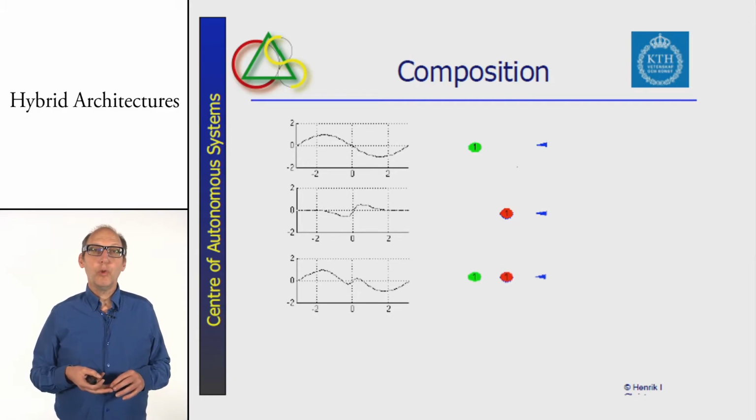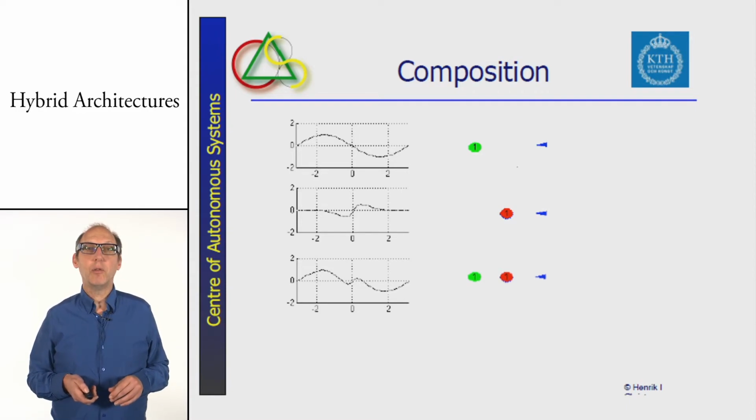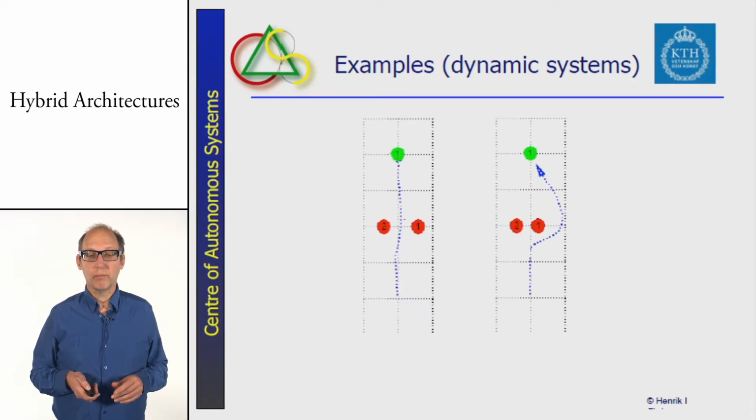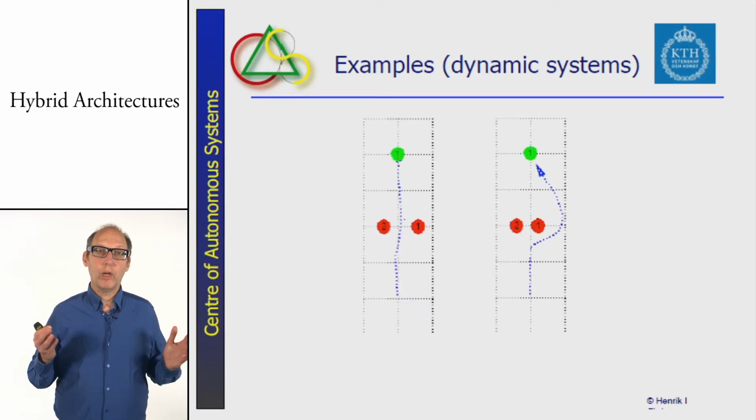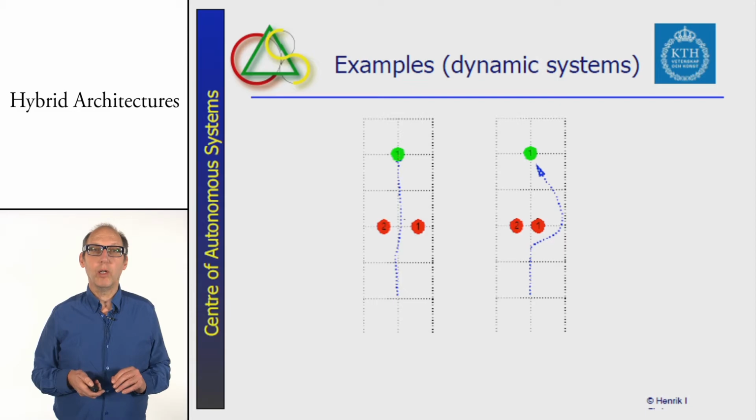And if you have such a vector-based approach, then you can make compositions, and you can combine planning with sensing information. In that way, if you have two obstacles in red, and you have a goal that you have to go through, then with planning you can determine whether you still have enough space to go in between those two objects, or whether your robot should go around.